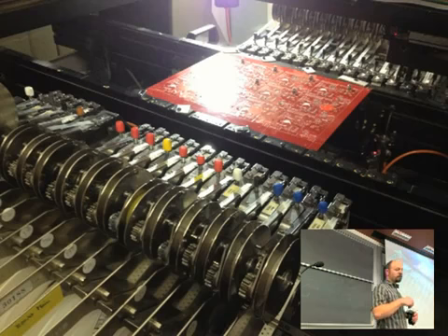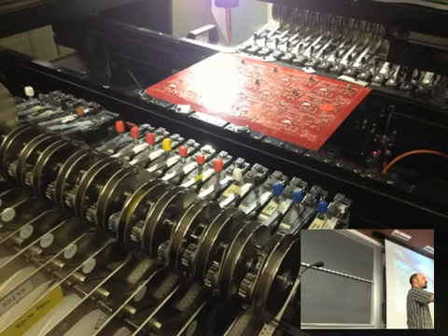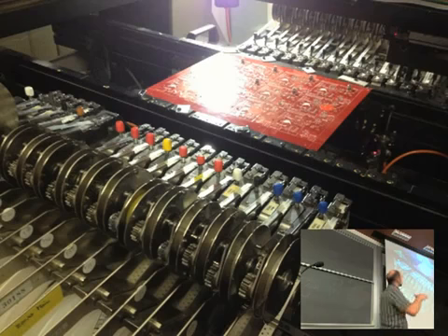Good point. So there is solder paste. Instead of putting solder on or just putting the parts on top, I actually left a step out in here, and that's the screen printing. What happens is there's solder paste that gets put on top of each and every pad. Solder paste is basically liquid solder that has resin in it to solder it together. It gets put on there, and then the parts get put on top of this solder paste. And the solder paste is good enough to hold the parts in place without any problem. There's enough friction and contact surfaces that they just stay there.